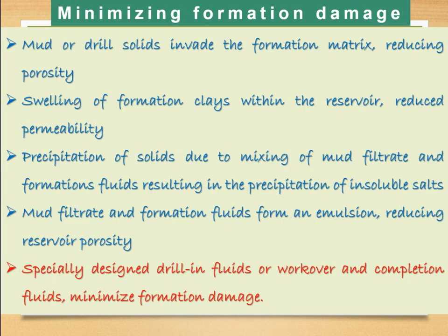Okay. Next, minimizing the formation damage. Yes, all are related to each other. The last slide is there, there is a link every time. So mud or drill solids invade the formation matrix, reducing porosity. And swelling of formation clays within the reservoir reduces permeability. So these are the natural problems.